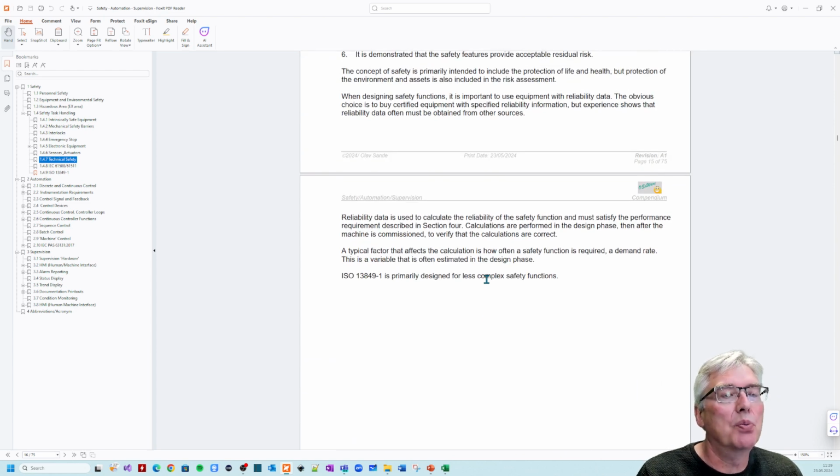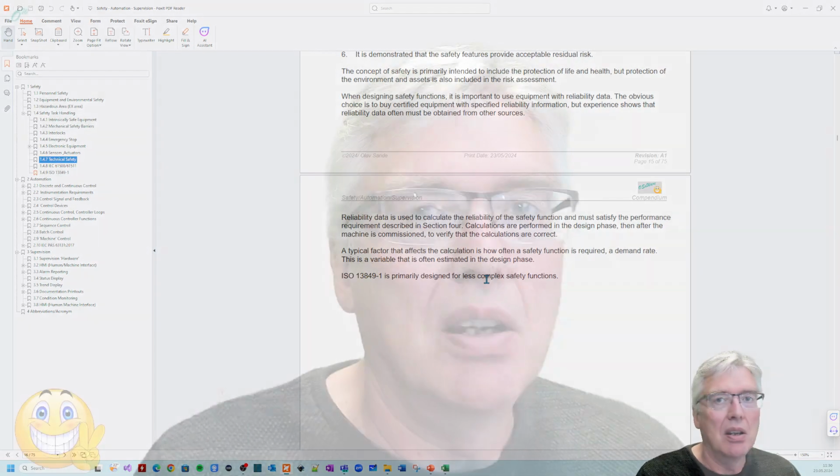So that was technical safety. So here we look at technical safety, and technical safety is achieved by a safety instrumented system of some sort, a safety PLC with instrumentation, inputs and outputs, sensors, actuators, and then the requirements. Here we looked a little at safety integrity levels.